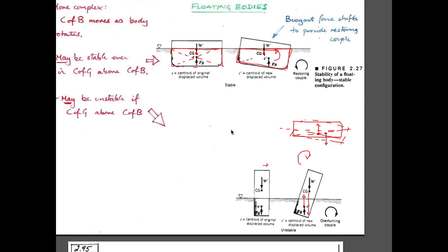So it all revolves around the fact that the buoyant force, which is always equal to the unit weight of the fluid that's displaced multiplied by its volume, acts through the center of buoyancy. That center of buoyancy is always the centroid of the displaced fluid mass that's present in the system. Okay.